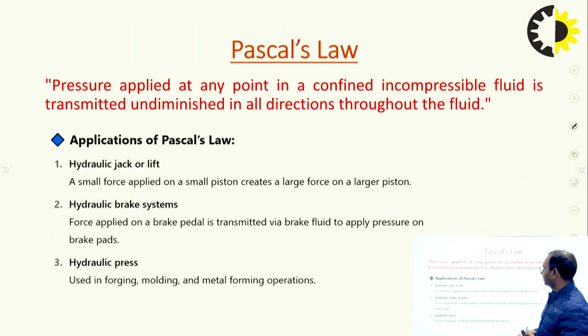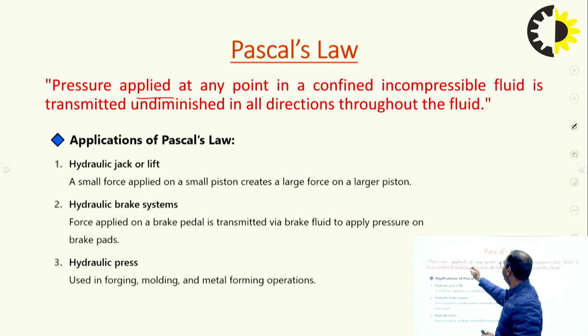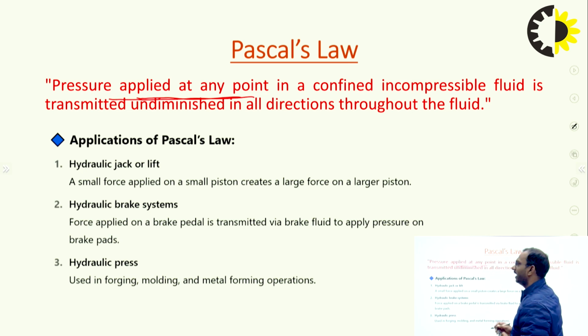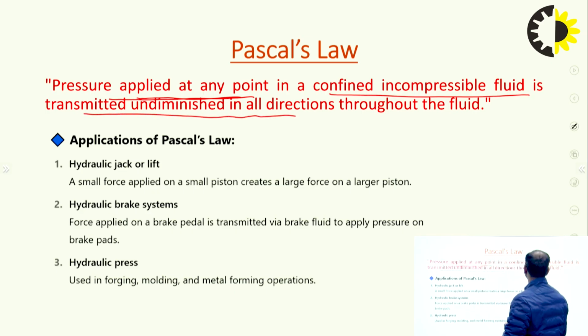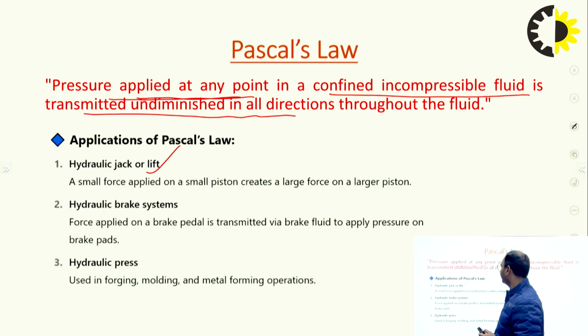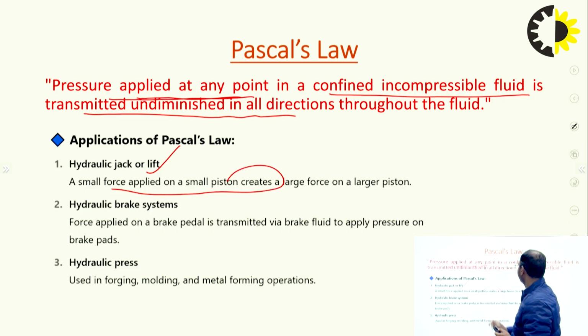Then what is Pascal's law? So, basically, according to Pascal's law, pressure applied at any point in a confined incompressible fluid is transmitted undiminished in all directions throughout the fluid. So, the applications of Pascal's law are the hydraulic jack or lift. A small force applied on a small piston creates a large force on a larger piston.